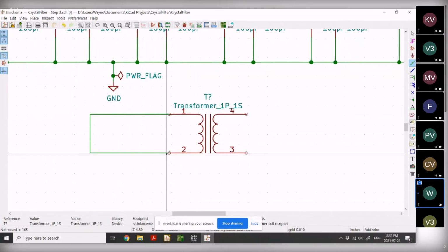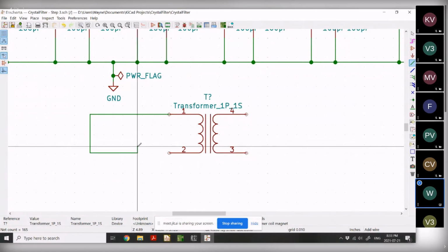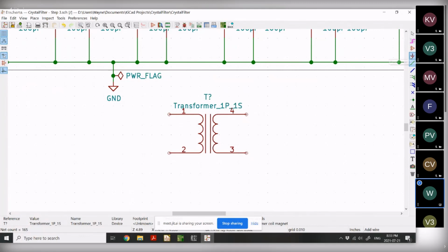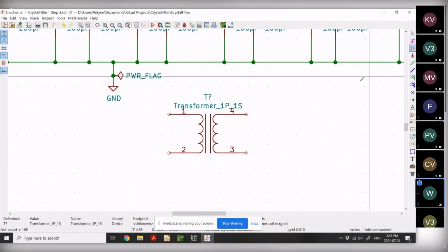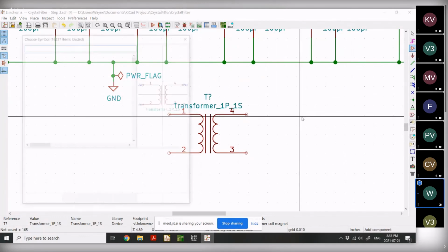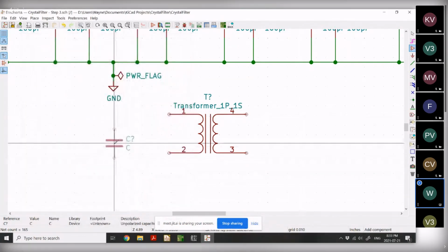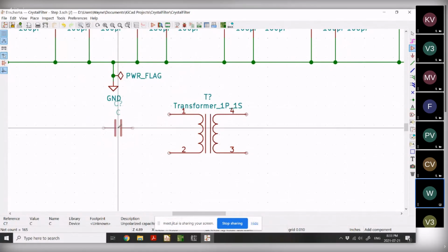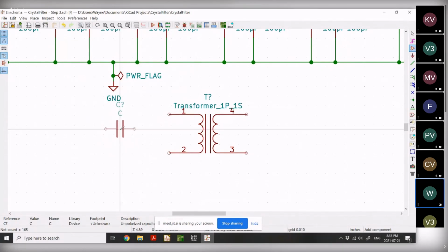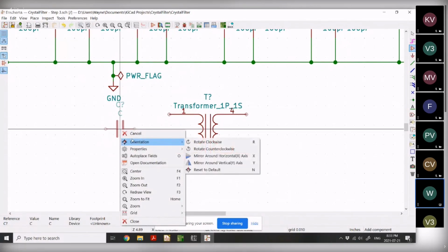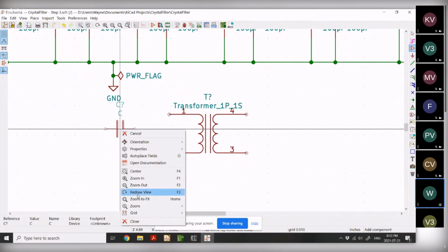You know, what's interesting is the wires snap to grid. This part did not. Do you mind if I do one more test or one more try? I want to drop a capacitor on. Okay. Wait, rotate, please. Why don't you try turning the snap to grid off? That's probably what's causing the problem. You can draw horizontal, vertical lines and right into your symbol and not be snapping where you don't want to snap to.